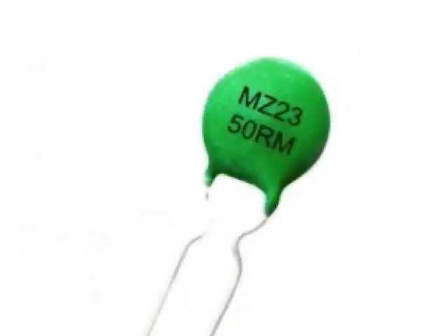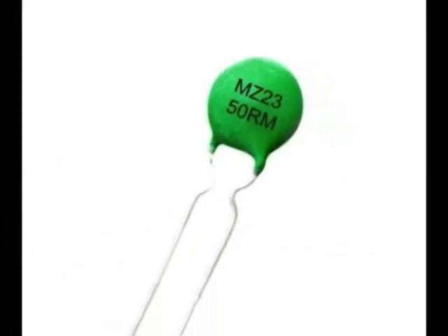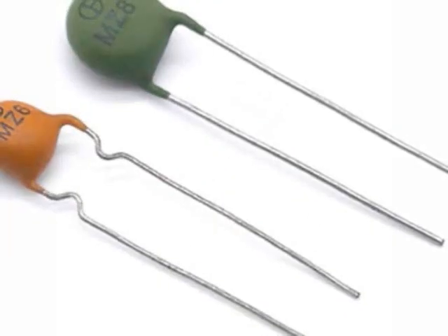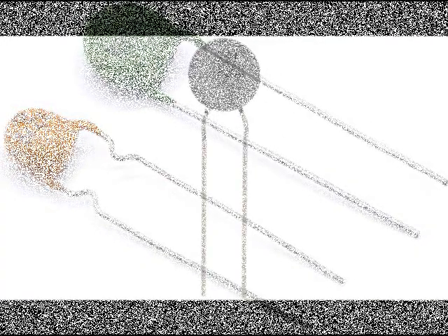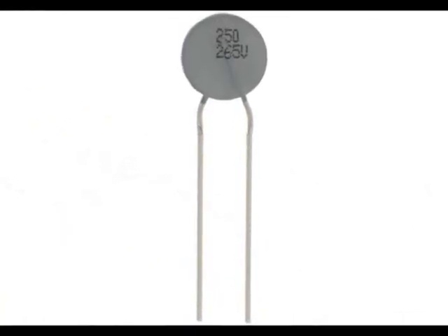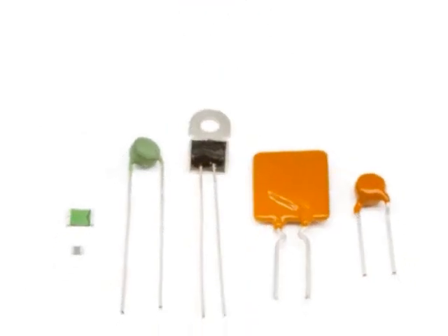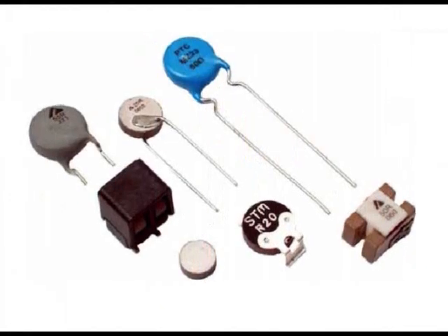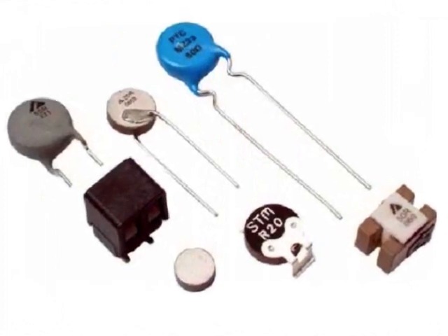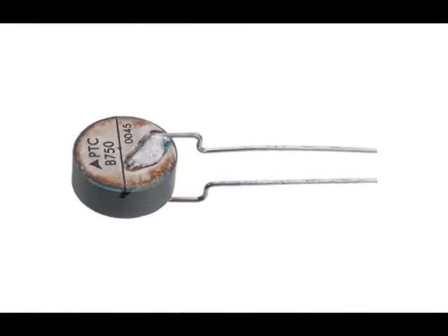That is, the temperature is obtained by measuring the resistance of the thermistor. Metals are used as PTC elements, but their electrical resistance is low. Therefore, in order to reveal changes in electrical resistance, the size of the metal resistance must be relatively large. For this reason, by creating the resistance in the form of a coil, its length increases and it creates a lot of resistance.